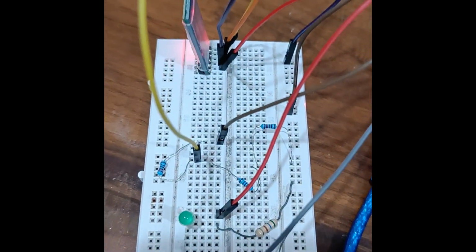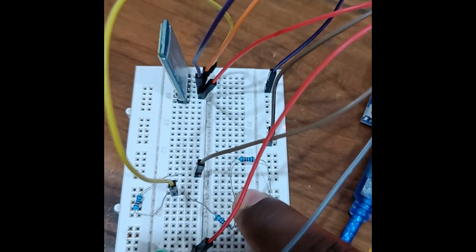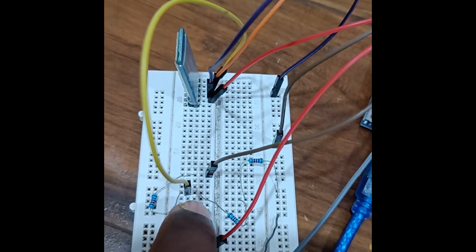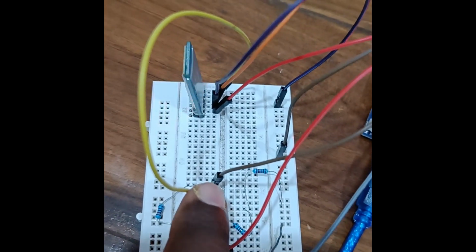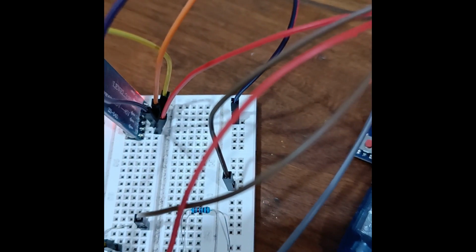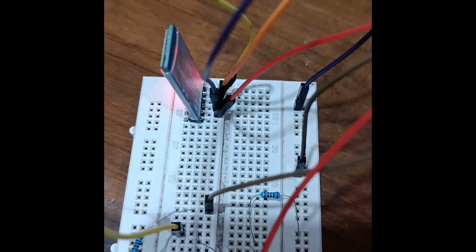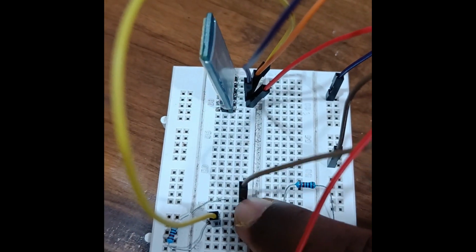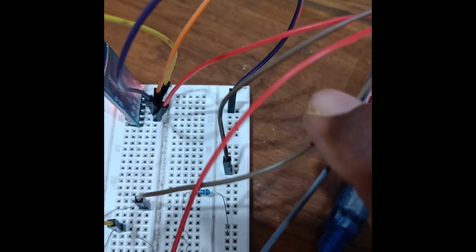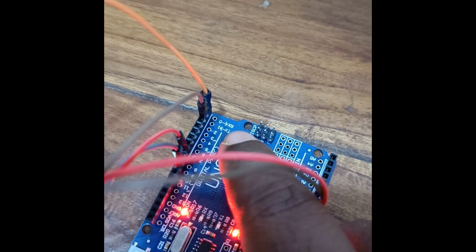Now coming to the Bluetooth module over here, you can see I have taken a voltage divider. This is a resistance, and this is again a resistance, and from between these two resistances of the voltage divider, I have taken this yellow wire to my RX pin. Now you can see this wire particularly. The resistance is ending over here, and from this I have taken this wire directly to the transmitter of my Arduino board, because the receiver is over there.